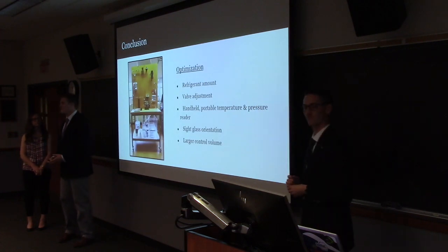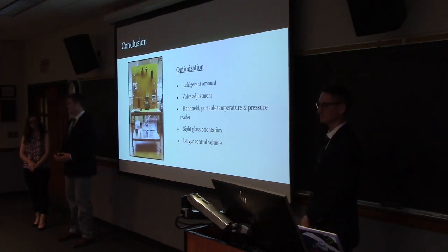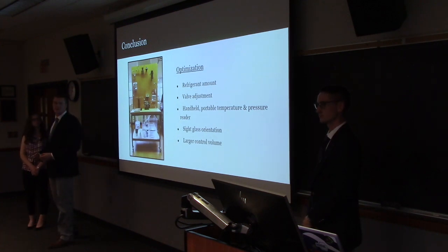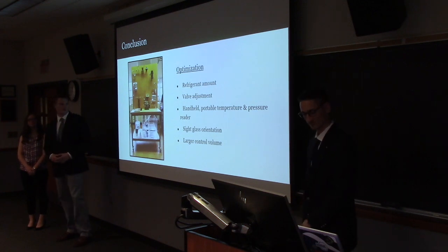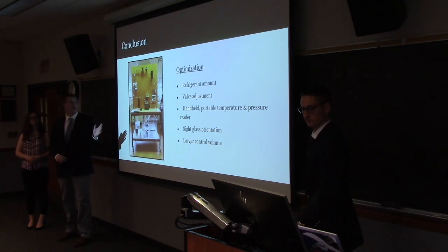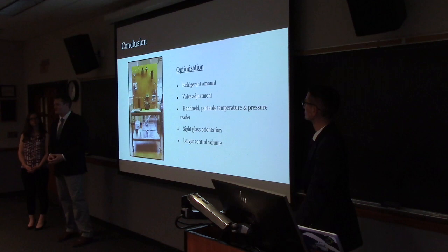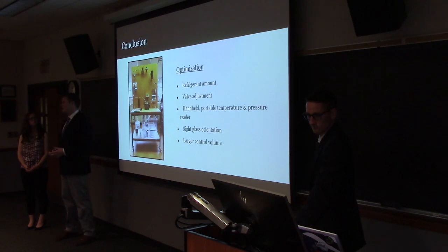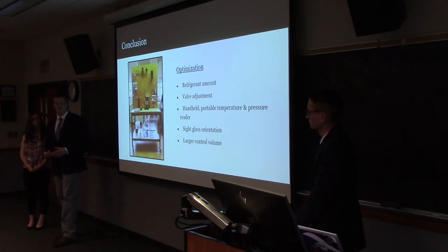So like Josiah was saying, we are happy with the board that we're able to present for the junior labs, but we still feel that there are some adjustments and some tinkering that we have to perform with the lab, so it's running at its full performance. The main thing that we should probably fix is the refrigerant amount. On the expansion valve, we wanted about a 100 PSI drop, and we only got about 85. This might have been due to a couple different reasons.